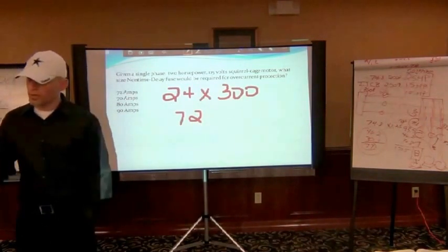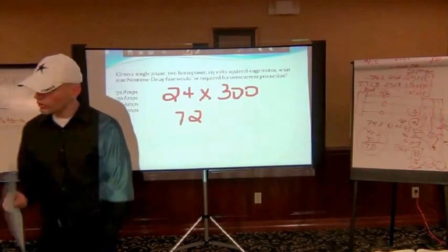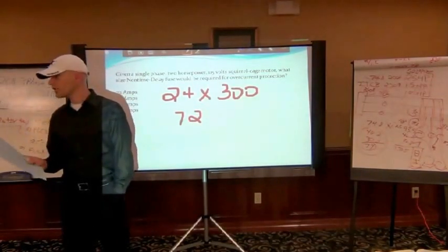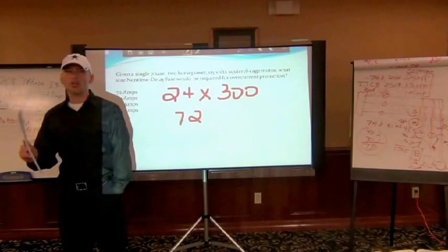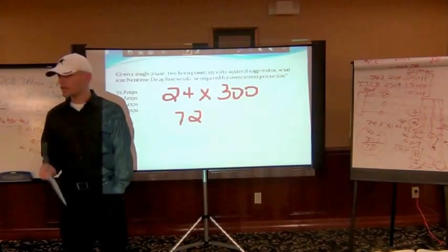125%. Burn that in your brain. A single wire for a single motor, or a single branch circuit set of wires for a single motor, is 125% of the table value every time, right? The only time that changes is if you have a different duty rating with a different time factor. That's the only time that changes.